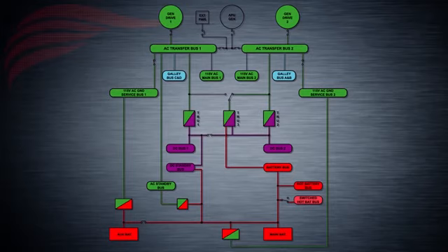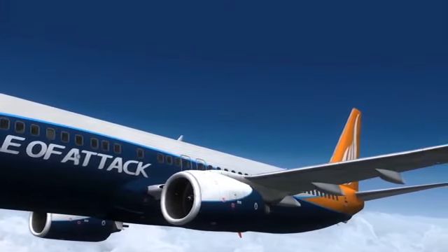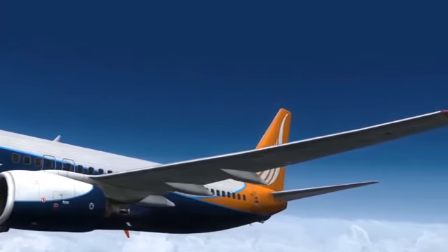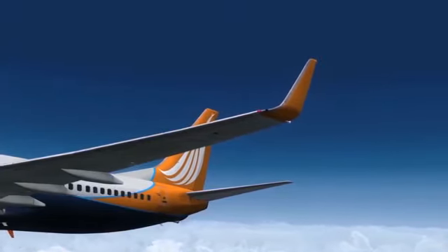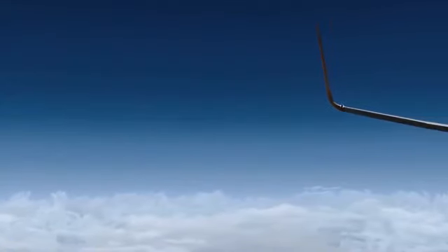through a relay. The DC system has 2 batteries, one main battery and one auxiliary battery. Both batteries are 48 ampere and 24-volt DC power sources. In very simple terms, the battery's connection logic is the following. The main battery normally only supplies power for APU starting, but is a standby power source when all other power sources are inoperative, such as during a complete loss of AC power if both engines are shut down in flight.